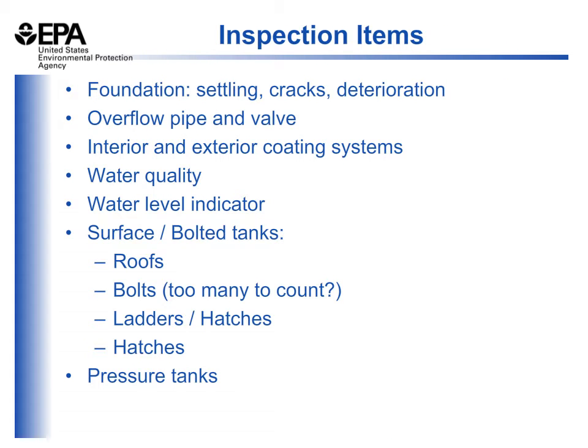During the tank inspection, you should look at the different elements of your tank, starting all the way at the bottom with the foundation. So basically, you're going to start by determining if the physical components of your tank are functioning as expected. You should also perform water quality testing to verify that your tank is providing good water quality, and check the accuracy of the water level indicators as they're needed to manage water demand.